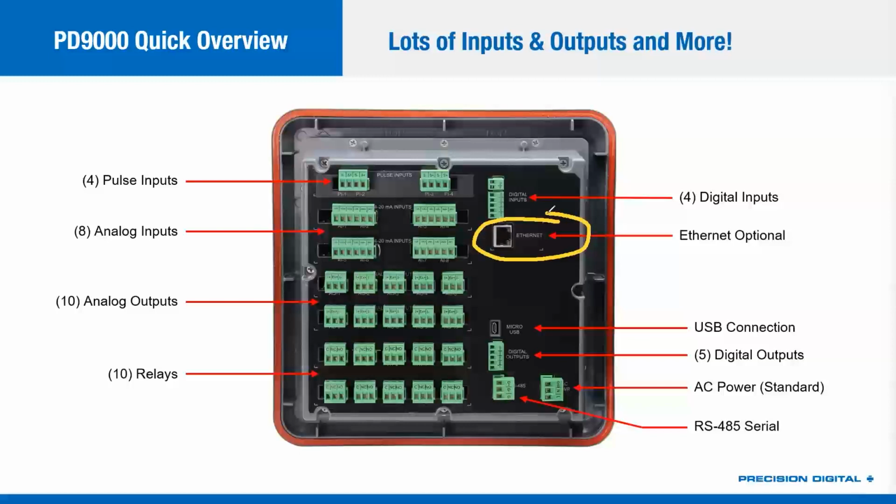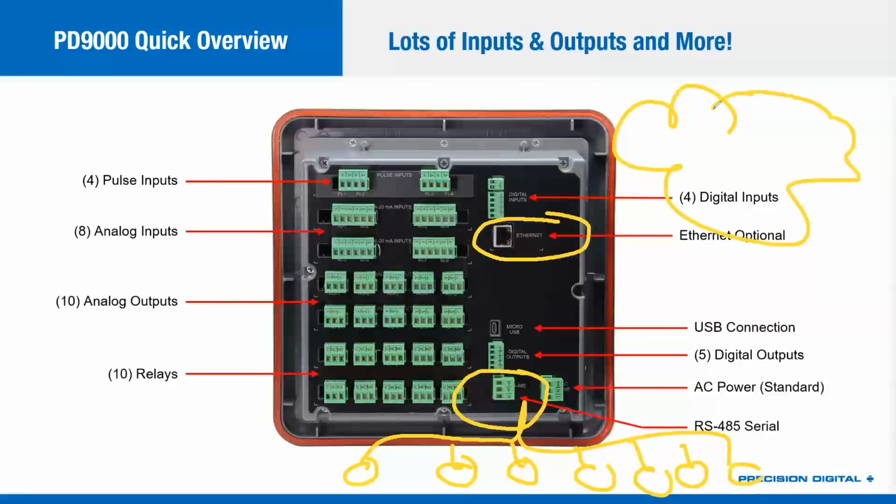So we now have Modbus Ethernet on a product, and that product is the Consolidator Plus. It's our first and currently only product with that. And what's really nice about it is it is a separate bus to the RS-485 connection. So oftentimes what I'll see with the Ethernet is they want to use the wired 485 bus to go out and connect to multivariable transmitters where the Consolidator Plus is a master. But then they want to have something in the cloud or perhaps a server in the same plant connecting to Ethernet, where in that case, the Consolidator Plus is going to be the slave. We can be the master or the client on the wired bus, and we can be the slave on the Ethernet bus.